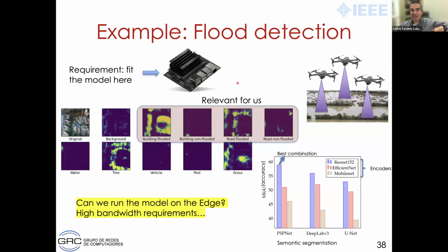For example, if you are detecting lost persons and you are flying too fast and you cannot process all the frames in time, maybe you miss the person back there because you are skipping too many frames, and the frame where the person was, you did not get to detect. So this is basically the summary of issues that we are right now facing when porting AI models to the drones.